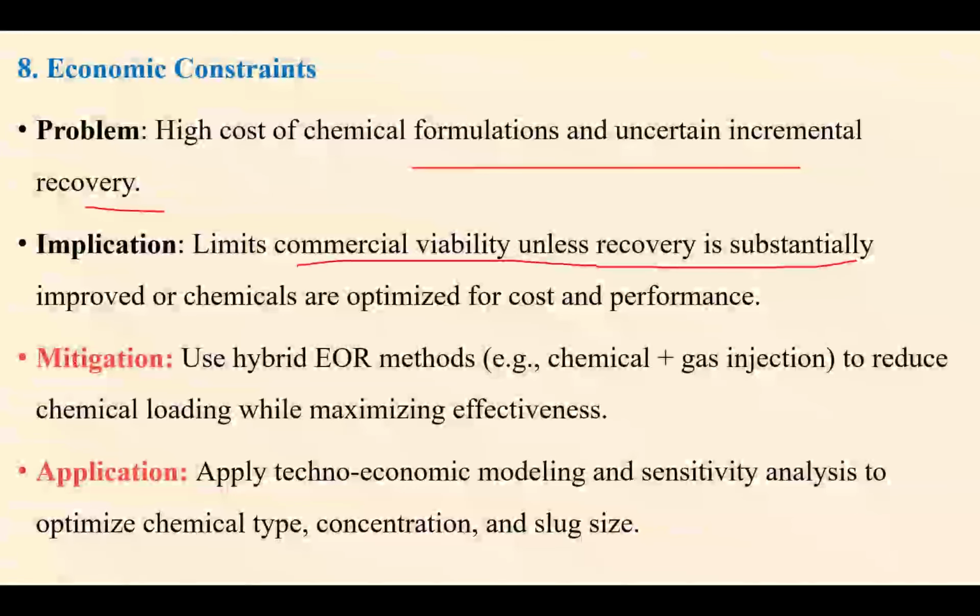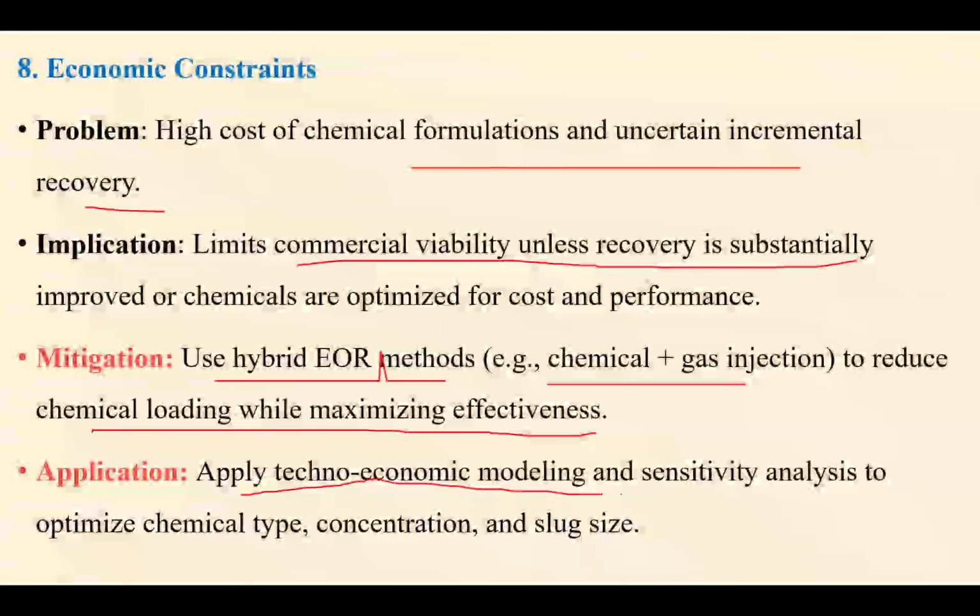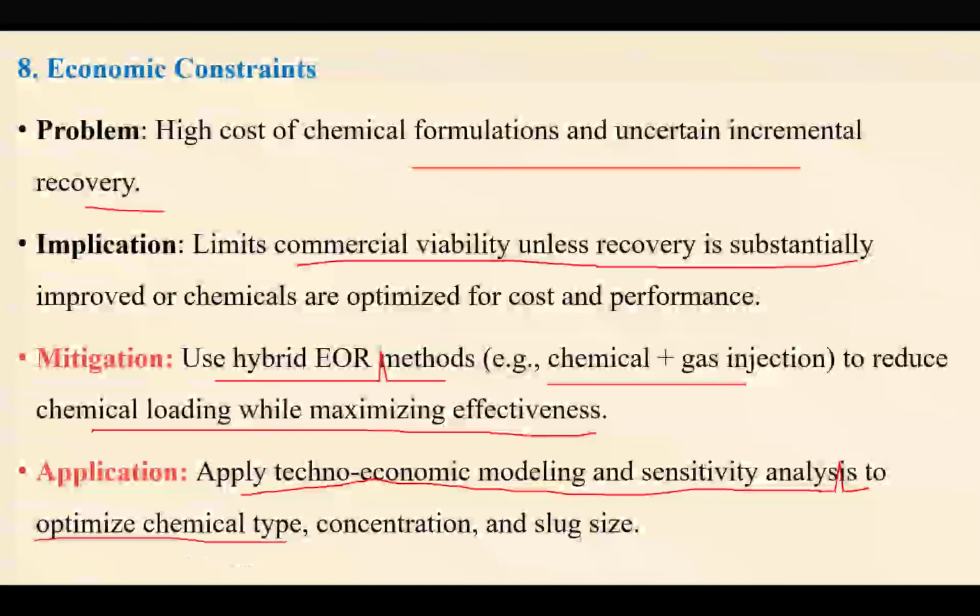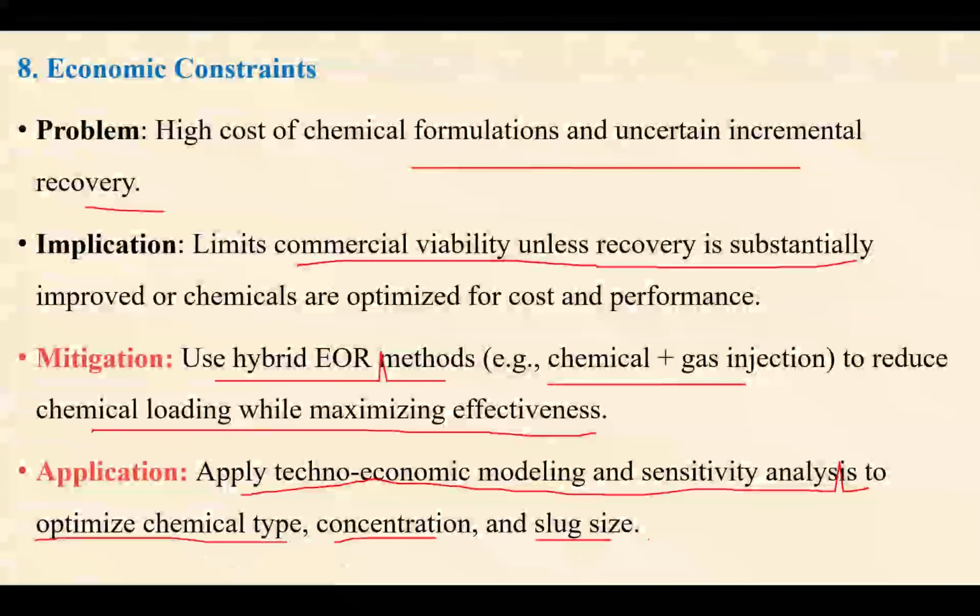Accordingly, with proper study, you have to go for some hybrid EOR method, like chemical and gas injection, to reduce the chemical loading while maximizing the effectiveness, and then apply techno-economic modeling and sensitivity analysis for optimizing the chemical type, concentration, and slug size.